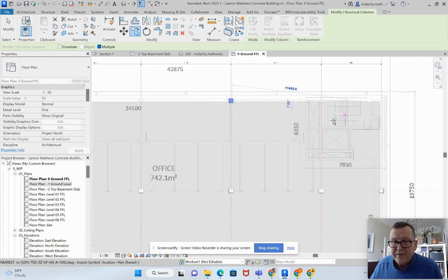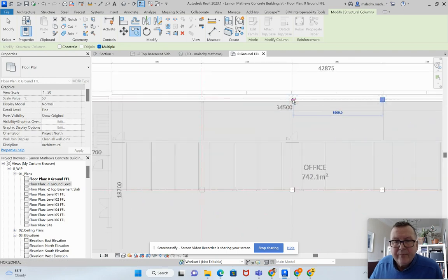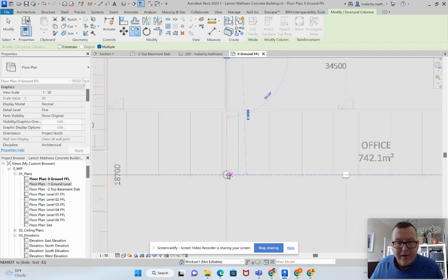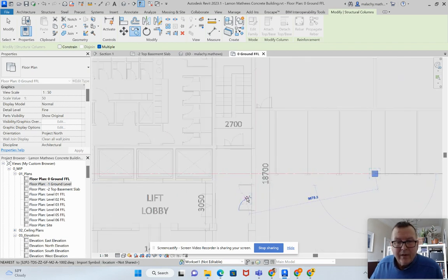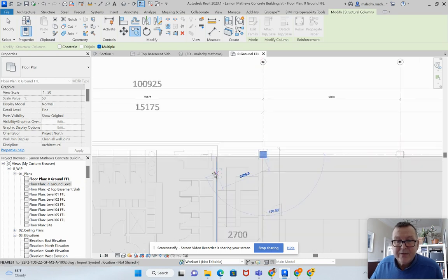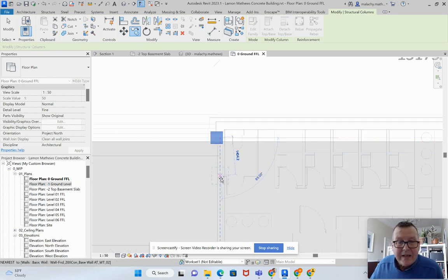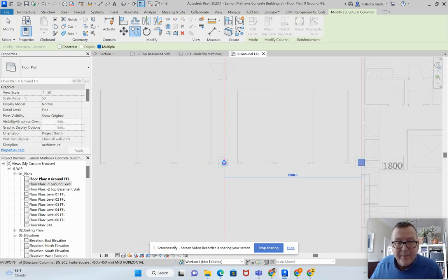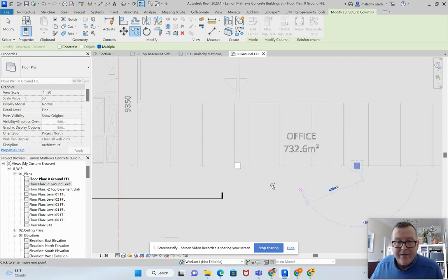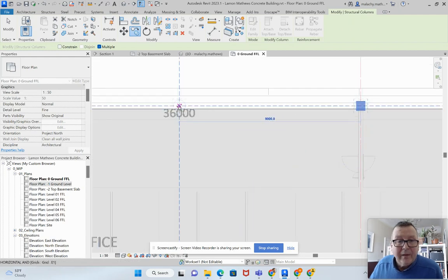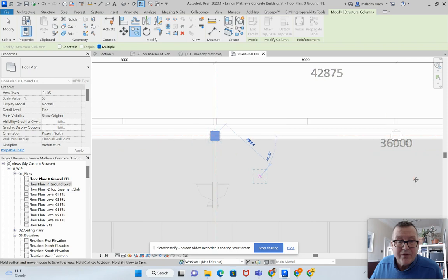Maybe there is one there because this is good. This is a poured core, so it's performing the duties as well of the column in terms of providing support here. And there's not one there, but I'm going to put one in there for the moment. There's not one there, but I'm putting one in here for the moment. And again, I'm going to remind you, this is me deciding that I wanted columns here. I'm just not sure why they were left out, because if you leave them out, then you have to make up something that'll act in their place in terms of a structure.